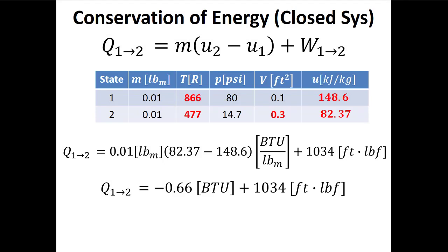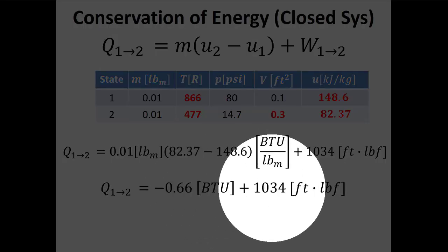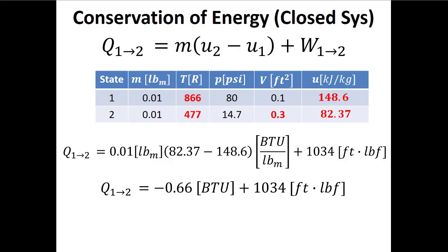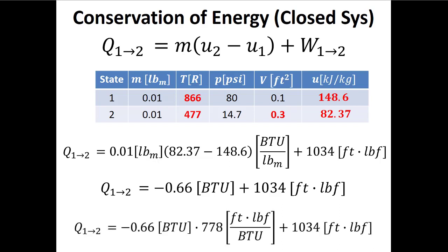But before, we saw that the delta U term was about half of the work term, right? So if you weren't tracking units, you might not see this, if you were going quickly. So we need to convert BTU to foot pounds.